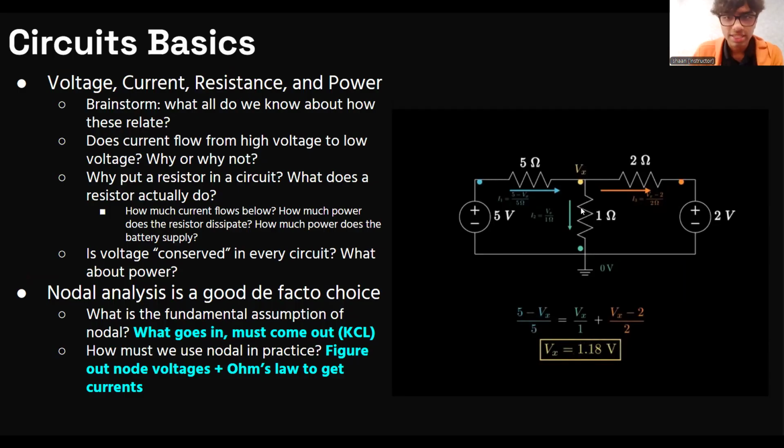I wouldn't read it as the size of the voltage source. I could draw this arrow in this direction, that one in that direction, or do it in another. It doesn't matter what direction I choose. What matters is that once I choose the direction of the arrow, I say it's this voltage minus this voltage, because we have voltage drop across resistors. Whether that leads to a negative voltage drop, meaning we chose the wrong direction and things are flipped at the end, doesn't matter because the sign does not matter. It'll end up working out as long as we're consistent.